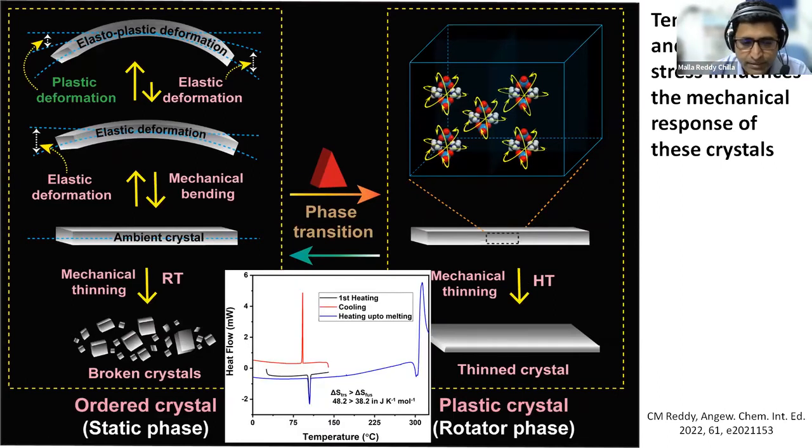Then we did the DSC for this. As you can see, this peak is much bigger compared to this melting. This is melting, and immediately after the melting there is a decomposition, which is why you see a big hump here. But essentially, this melting peak is smaller compared to the solid-to-solid phase transformation, where you have an order to disorder transformation.